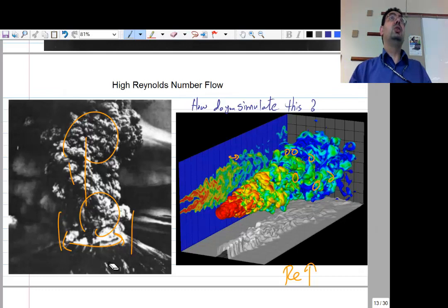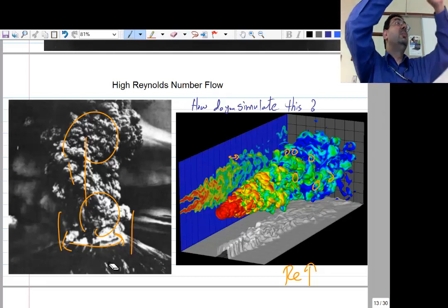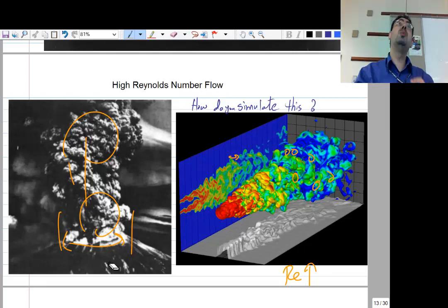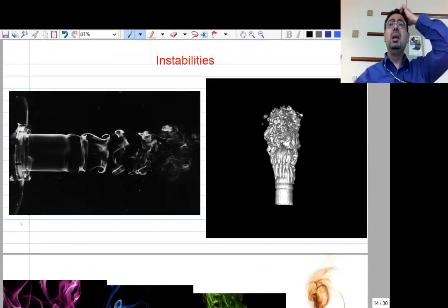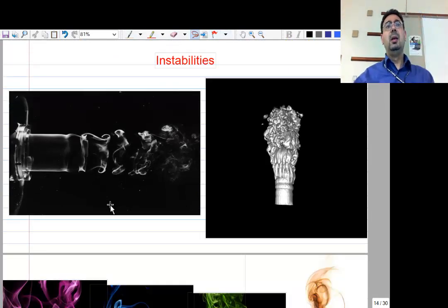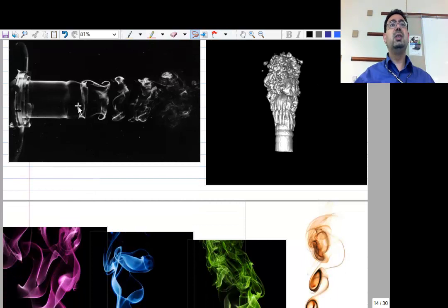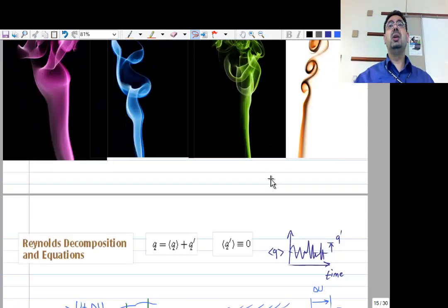And so they made this kind of energy cascade model. They realized that the flow gets its energy at the large scale, and then it is passed to the smaller ones, and smaller ones, and smaller ones. How small it will get is controlled by how high the Reynolds number is. Here are more cool pictures of how this gets initiated. The large scale structures start to form first, and then smaller ones start forming, getting energy out of them.